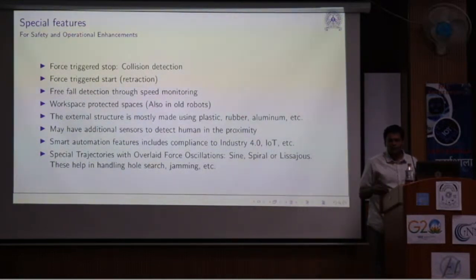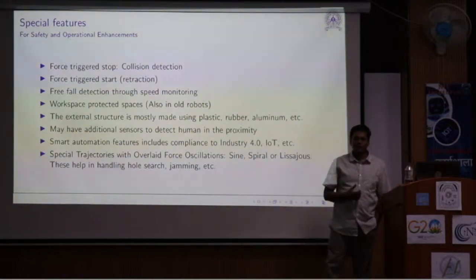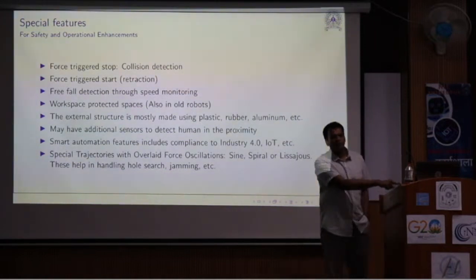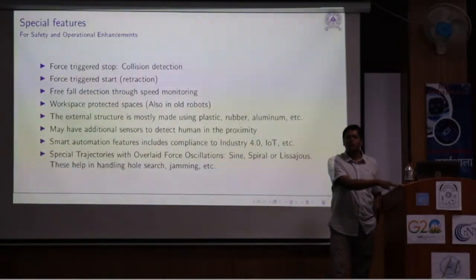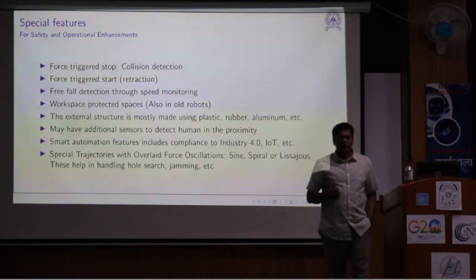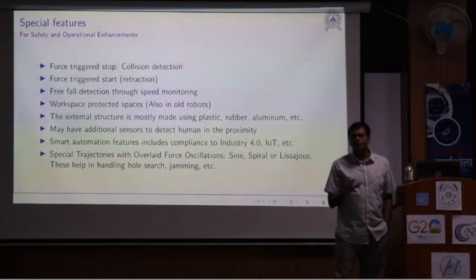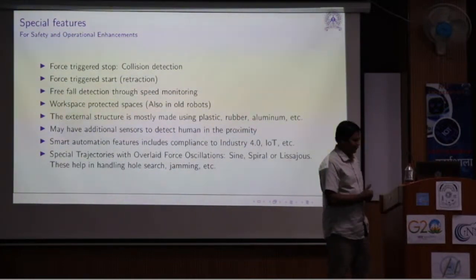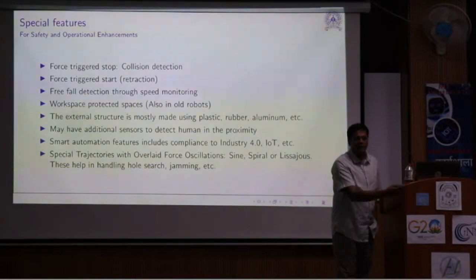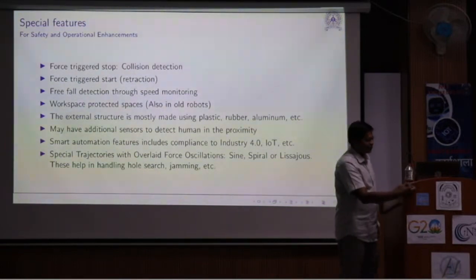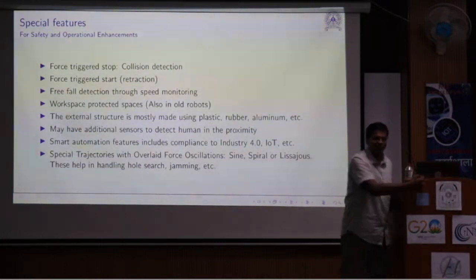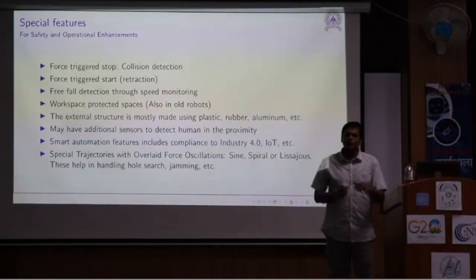So there is a position trajectory, and it also has a force trajectory. What does that mean? At each and every point, how much is the force? What should be the direction of force, where you want to be compliant? Let's say I have told it normal to the surface, I want to maintain 10 Newton. Okay, it has a very different meaning, because the normal is changing at every point, the surface is curvy. So the normal is like this, like this, like this, finally like this. Is it not? So the normal is changing, and so is your trajectory.